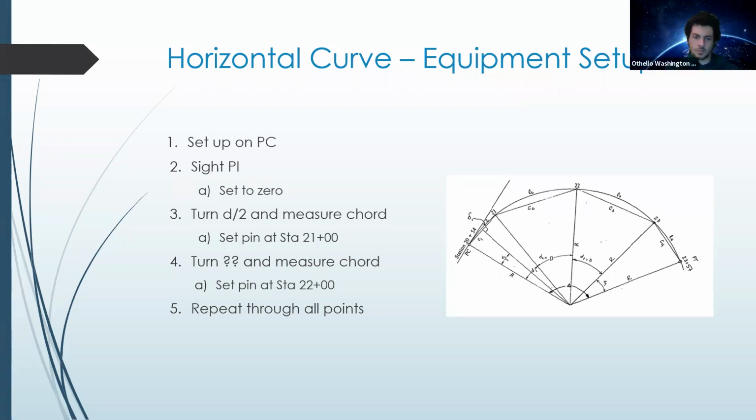In between, it's a 6.9, right? 6.9 degrees, perfect. Yes. Then we're going to measure the chord length, because that's a nice straight line. So if we measure out that chord length, which we also calculated to be 45.92, there's our station 21. Okay.